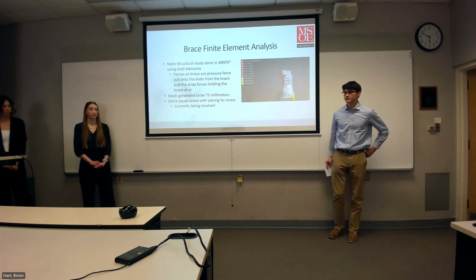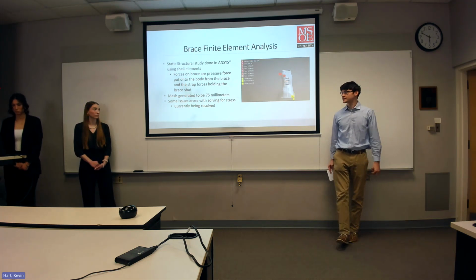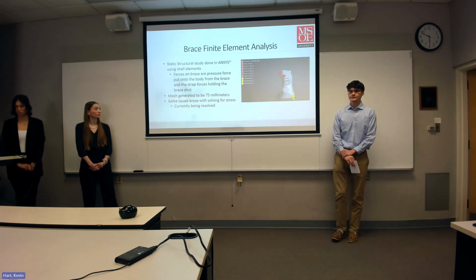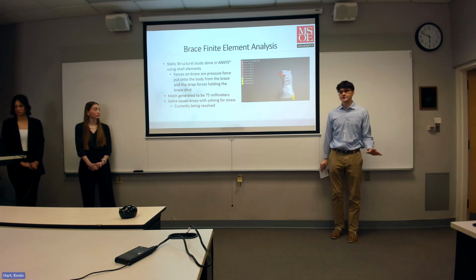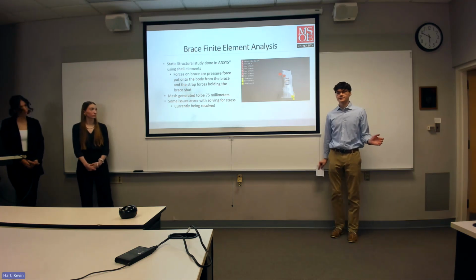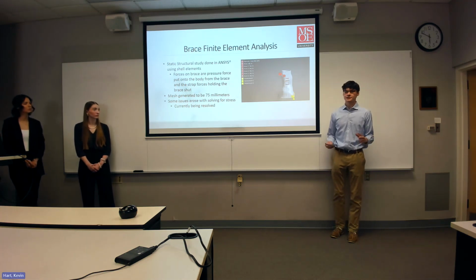To generate the mesh, it was set to be 75 millimeters. This was a good enough size to have some variability in the stress results, but it also didn't take too long to generate.